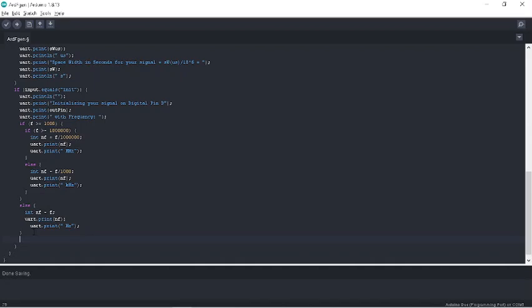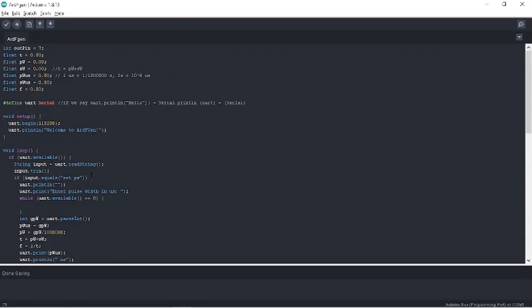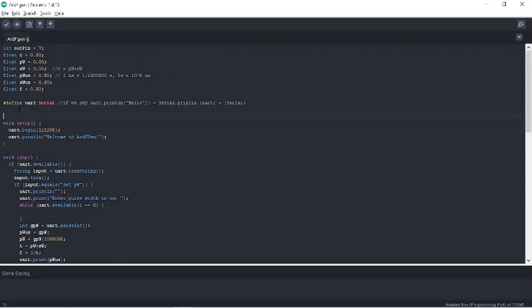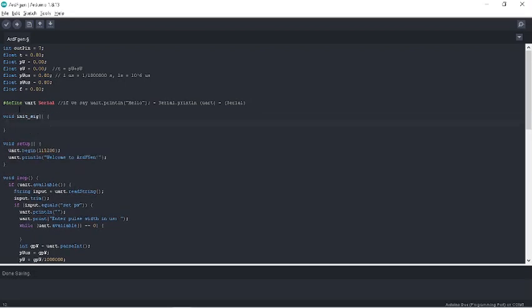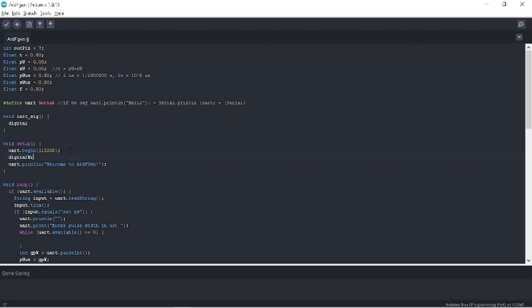After this we are gonna make a new function called init signal. So this is our function name. Let's say the function here initialize signal. Okay, now initialize signal is pretty easy. It's really easy. Okay guys, first in this also ur dot begin, we are gonna say digital write out pin comma output.